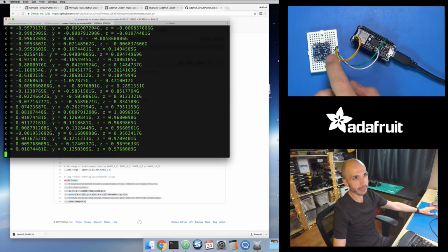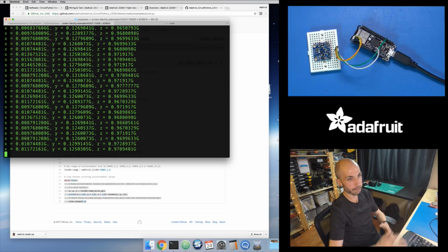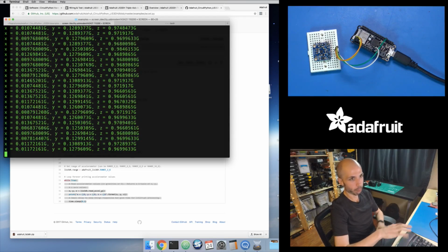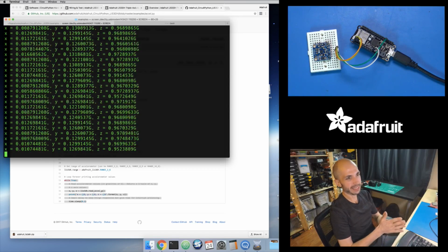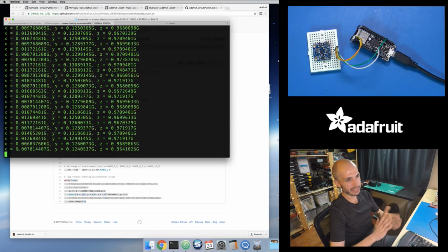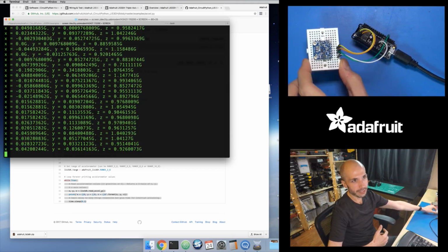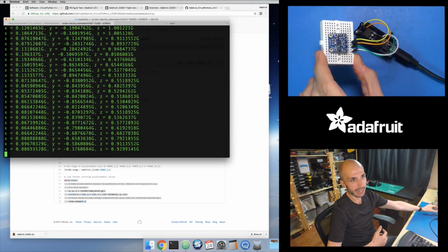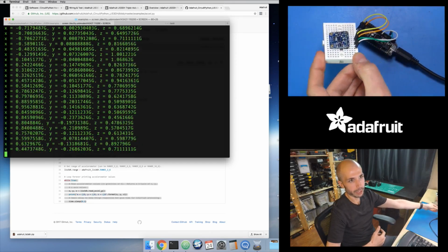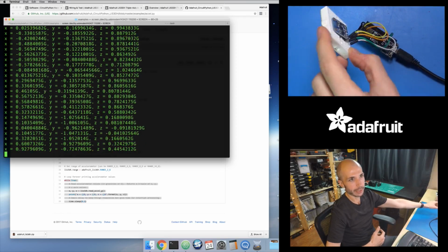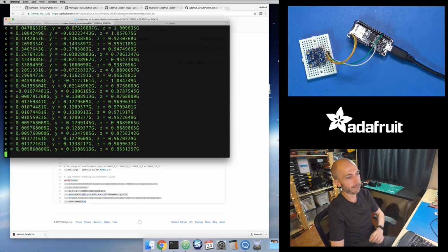So that's pretty cool. You can imagine putting this in a cube, and then you could tell which side of that cube is facing down just based on which axis sees roughly 1 g of acceleration. Pretty cool. And you could actually do this if you had a 20-sided dice. I think Phil B has an awesome talking 20-sided dice project. Again, you just have an accelerometer mounted in the center of it, and then based on how those axes return values, between 1 and -1 g of acceleration, you can tell how this thing is oriented relative to the ground with Earth, where gravity is pulling it.